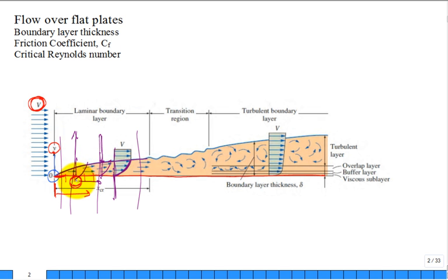One of the things about this velocity profile is that it looks pretty similar. And somebody observed that over 100 years ago and worked on a mathematical description of especially the velocity profile and the shear stress. Because what you're very much interested in is, what is the shear stress right here? Let's call it tau, on the y surface in the x direction. What is that shear stress, so that I could calculate a drag force on the plate, the net viscous drag? Well, if we could get the local shear stress at that surface, we would then sum up over all of the surfaces by integration, and then we could calculate the net drag.